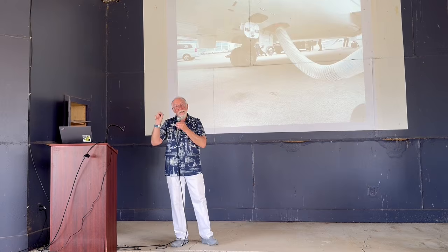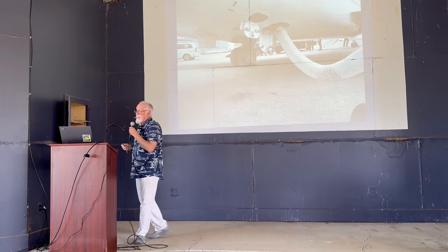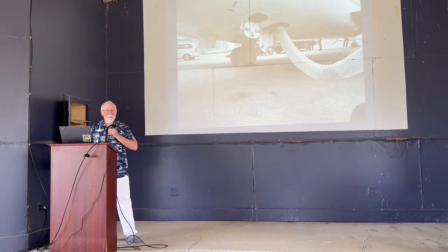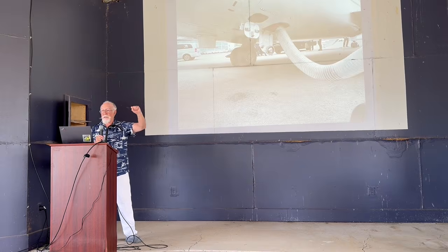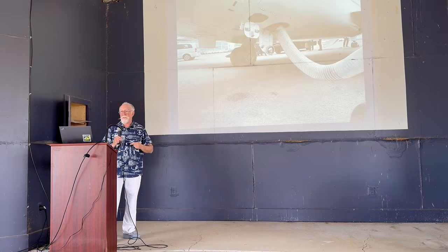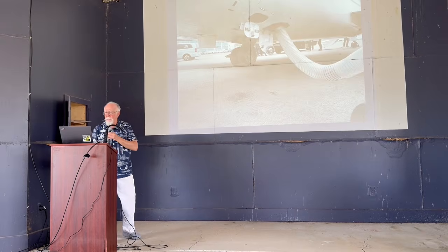Because if it doesn't unplug really cleanly, they need that PPE. So, there's those kinds of considerations. For example, I know of one airplane where the ground start APU plug-in is on the same side as the engine you start first, which saves a few inches of wiring. It'd be a lot safer to have it on the other side, so you plug in on the right side and start the left engine, just for example. Ease of loading, all kinds of things like that come in.